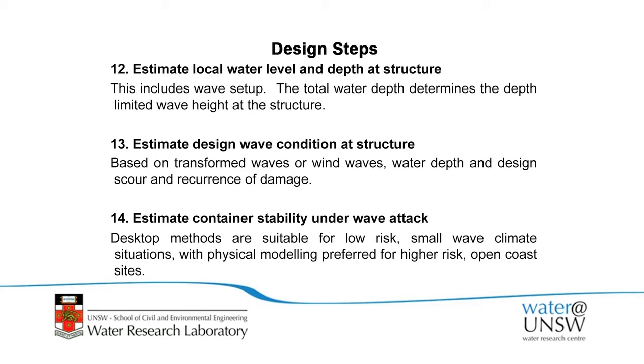And the desktop methods are suitable for reasonably low risk or for small wave climate conditions. If there's a lot of risk in the project or reasonably big waves at the limit of the structures, it's certainly recommended, as it is with rock structures, that physical modelling is undertaken.